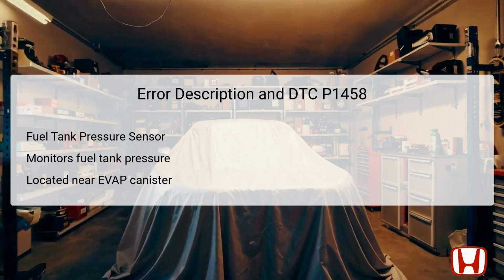The fuel tank pressure FTP sensor is integral to monitoring the fuel tank's pressure levels, which is essential for the evaporative emissions control system. Located near the evap canister, this sensor communicates vital pressure information to the powertrain control module, PCM. An error occurring in the FTP sensor can lead to the triggering of DTC P1458, indicating that the sensor circuit has a range or performance problem.